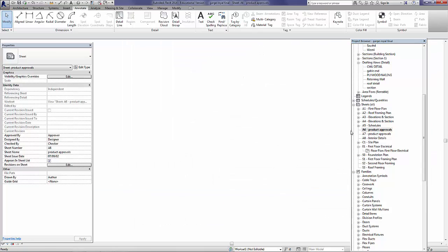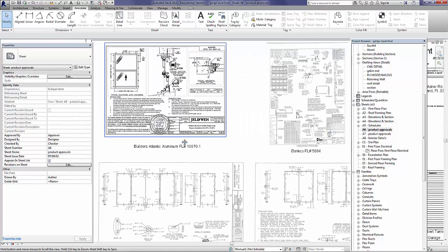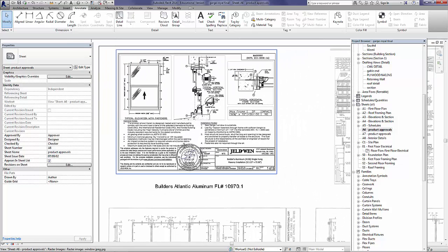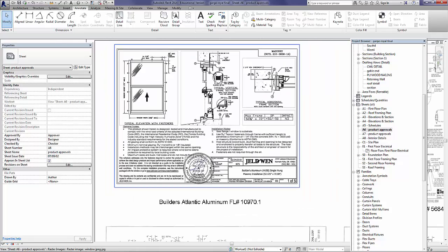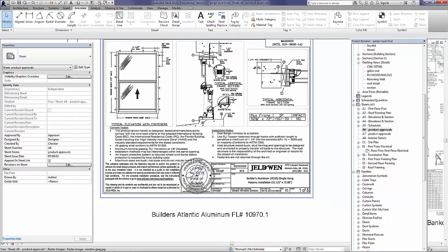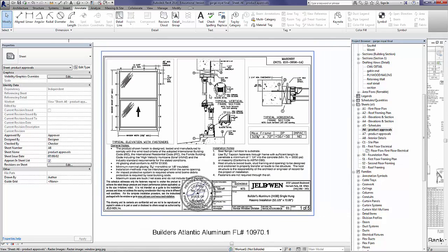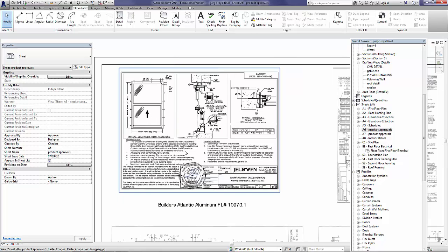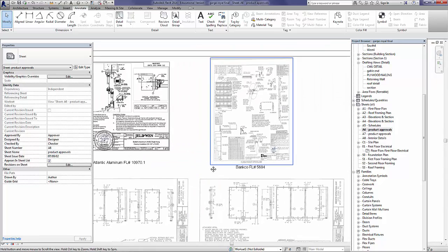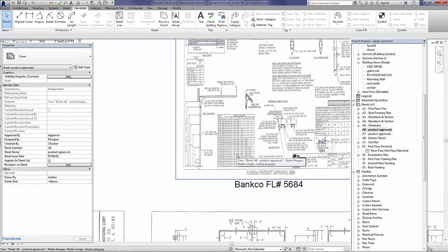Also, I've got the product approvals, as you can see here. The reason we do that is we go to floridabuilding.org. We get the different product approvals because we want to show how to install it properly to the contractor, so we can also prove that it was tested for a 2x4 being shot towards it and not breaking, so it was able to sort of crack but not fail, which would be happening during a hurricane type situation.